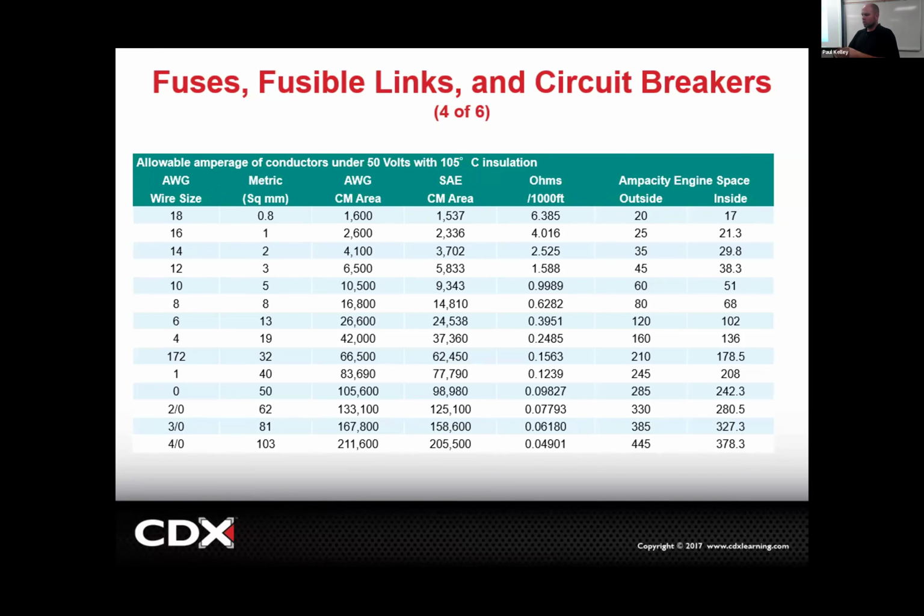Makes sense? So when you see a fuse, the reason it's in there is really because of the wire size, what the wire can handle. If you follow that logic, then why not say, you know what, 14 gauge is better than 18, let's just run 14 for everything? Why would that not make sense? Think of it as a business.